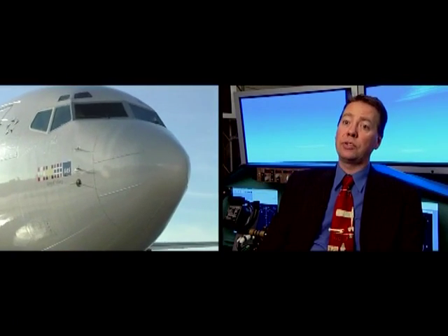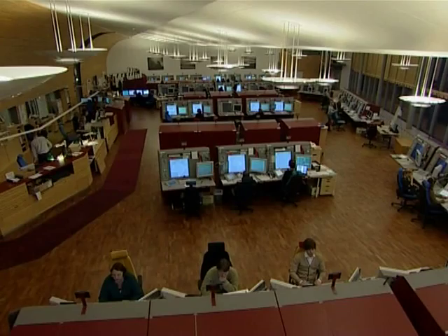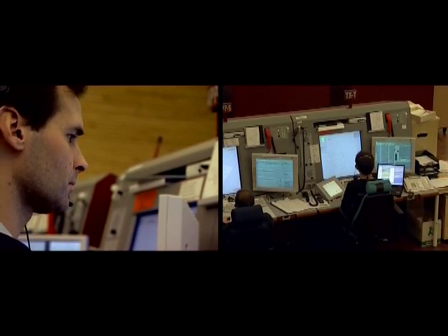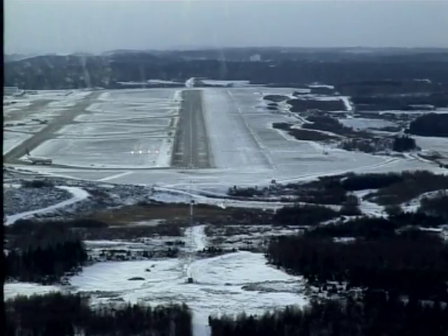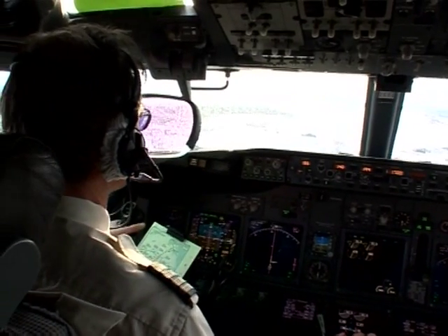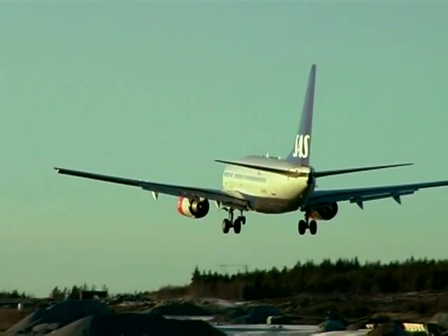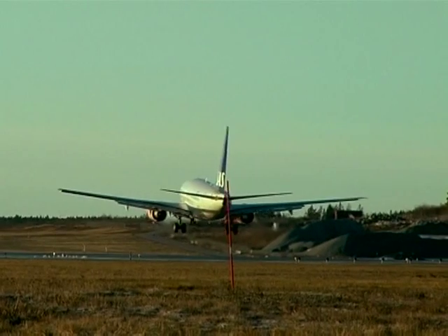The big change now is that we have been able, together with Boeing and Smiths Aerospace, who builds the flight management system, to open up so that we can take data out of the system and link it to the ground system. The flight will start with the controller accessing the computer system on the aircraft to see how the flight will go into his sector and his airport. And basically what you do is you assess if it's in conflict with other aircraft that are coming in at the same time. If it is in any conflict, you have to adjust the flight path. If it's not in conflict with any other aircraft, you let the aircraft fly its optimum flight profile.